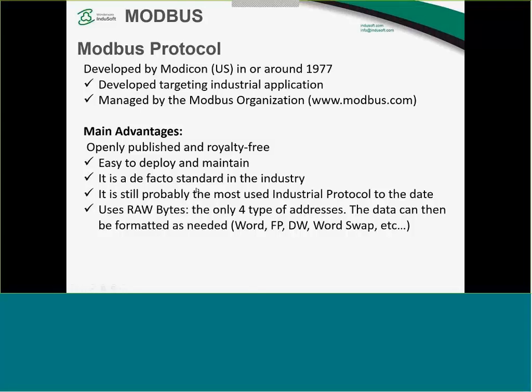Basically, it's proven how easy it is to implement and how easy it is to find devices out there that speak Modbus, all the way from RTUs to motion controllers. When you have a new PLC on the market, it may come with a proprietary protocol, but they're going to mention that we also speak Modbus. So that's why it's probably the most used industrial protocol to date.